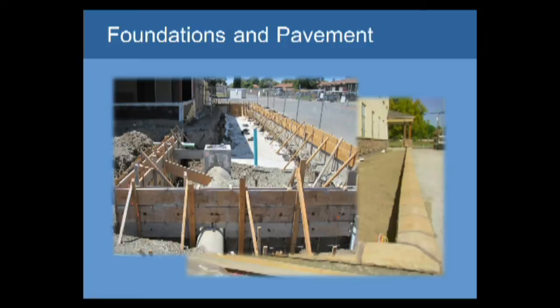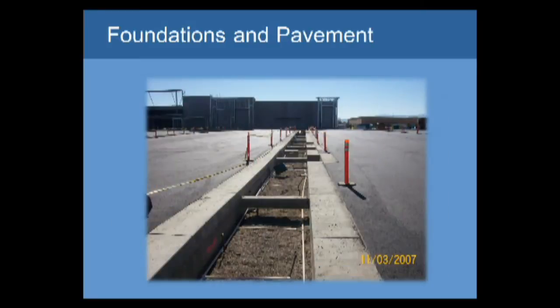This is in shrink swell clay soils. This is also in shrink swell clay soils. What I want to point out here is the error on this project. They got this side right where the building foundation is. What they didn't anticipate was that this street is going to fall into that excavation eventually, and they ended up putting in, what do you call it, little wing walls or whatever to hold up that wall. Here's another example of the same thing being done with these little bridges to ensure that the bioretention facility walls don't start turning inward.